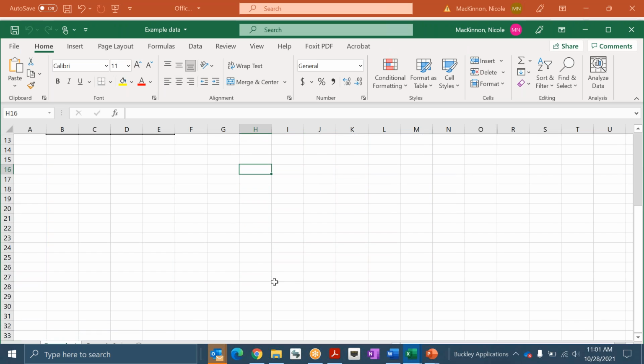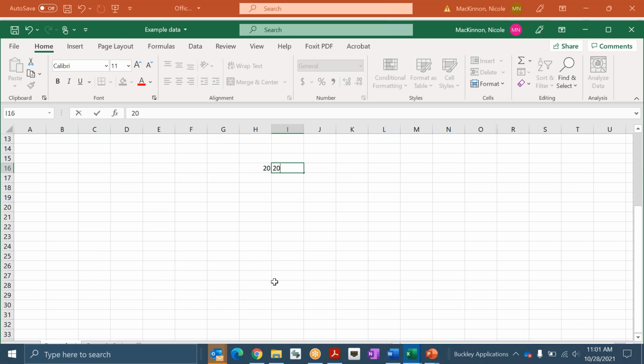Going back to some quick math, maybe my area is a 20 by 20 room, and I'm making some assumptions. This may not be accurate. 20 by 20 space, and I'm going to use 100 BTUs per square foot, which is very high. I would say in most scenarios you're going to see about 15 to 35 BTUs per square foot.